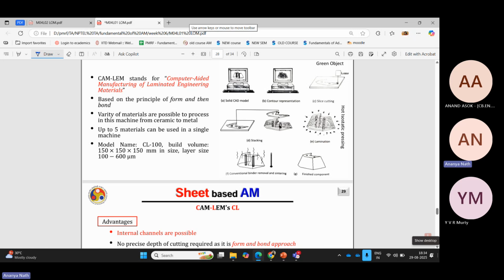In sintering, there will be pressure and temperature at the same time, through which the ceramic sheets or the ceramic powder join together, and there will be no porosity in between. That is the sintering operation.